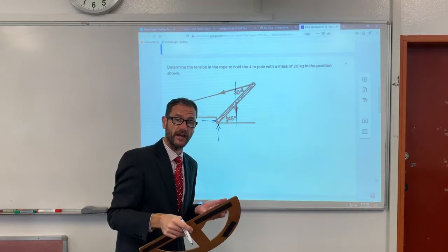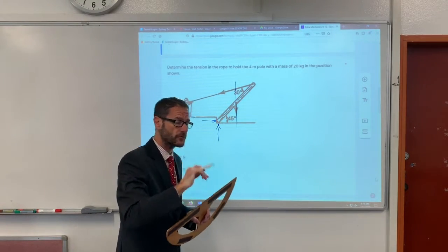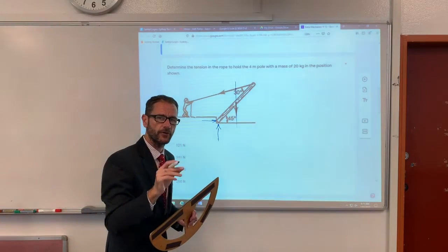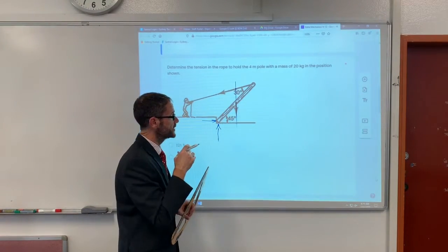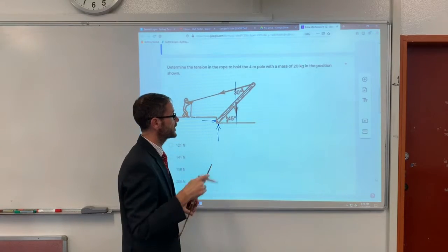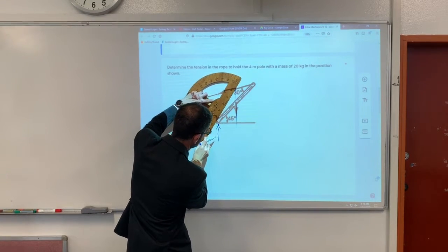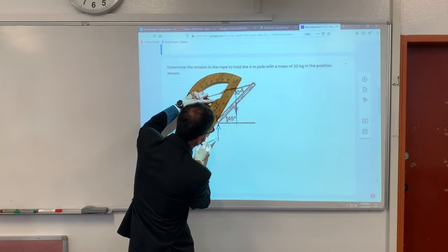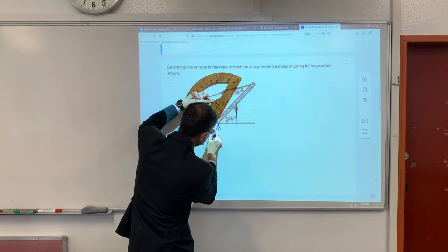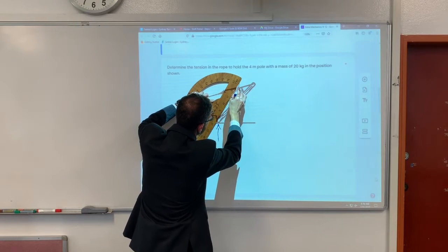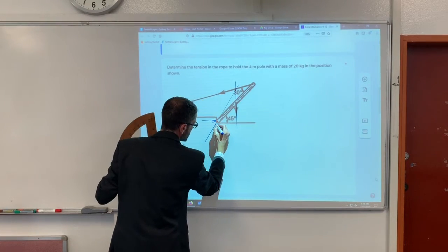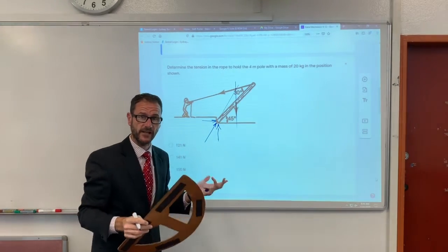What is the direction of that reaction? That's unknown, except that with the 3-force rule the forces are either parallel or concurrent. Quite clearly in this situation they're concurrent. So there's our point of concurrency, our point of application, and our reaction is down here like so. We can extend the line of action to show that.